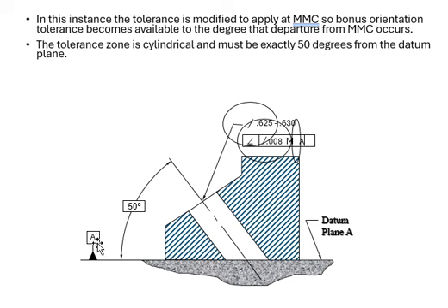We're going to call it A, and put a symbol to identify that plane. We're going to measure that, and you get like 50, and your measurement has to be from that plane all the way to the center of that hole, which is your axis right there. And we're going to give our specification as 0.008. Okay, that's just showing you the circles right there, so you can see. This is kind of off, so that's supposed to be datum A.